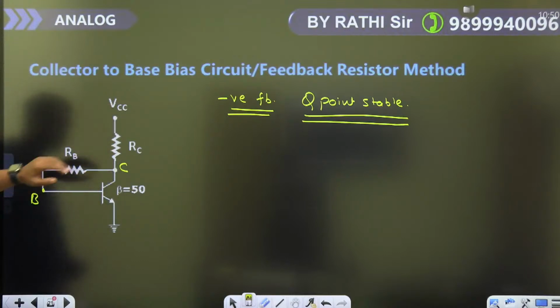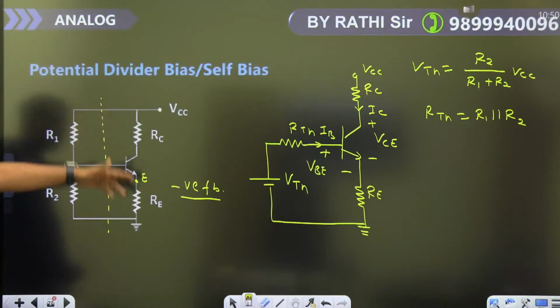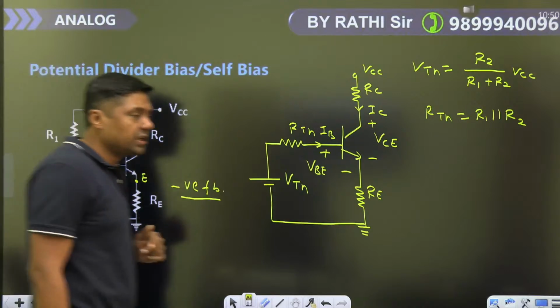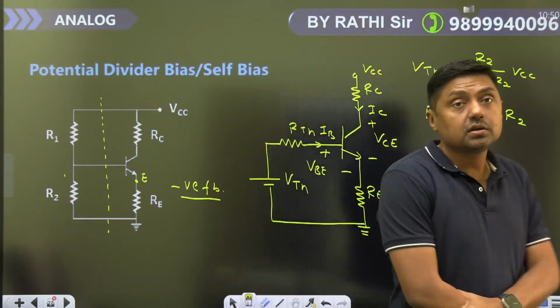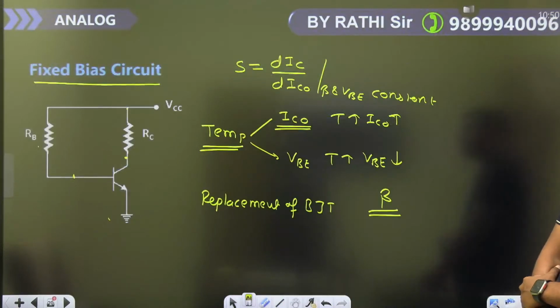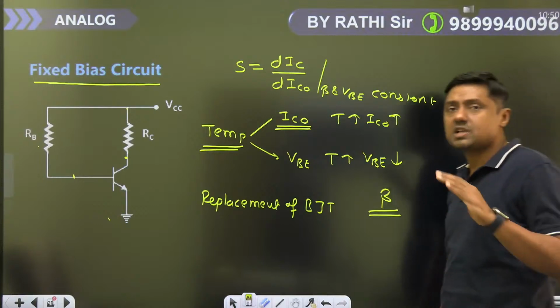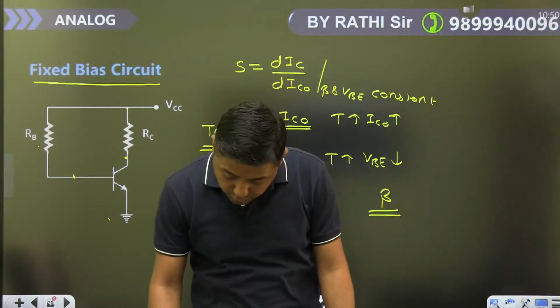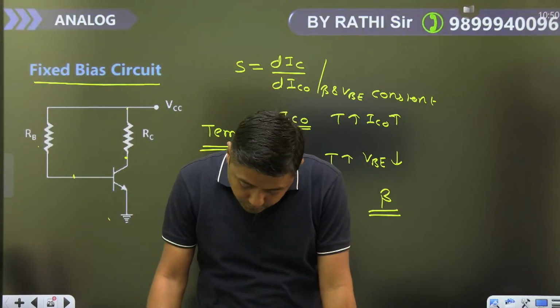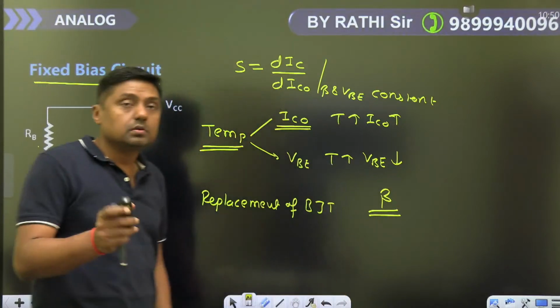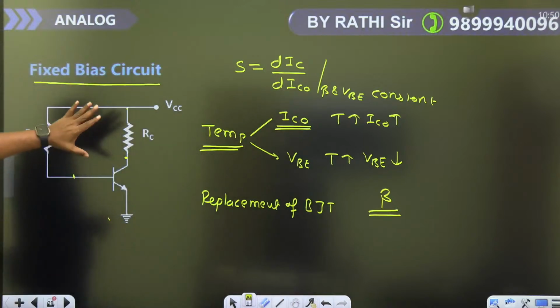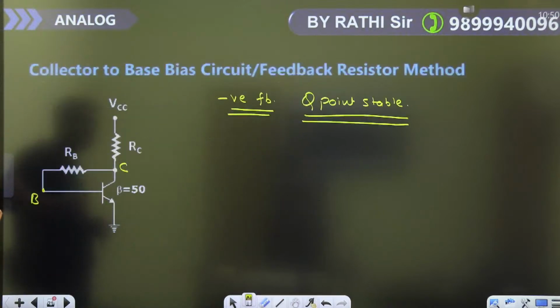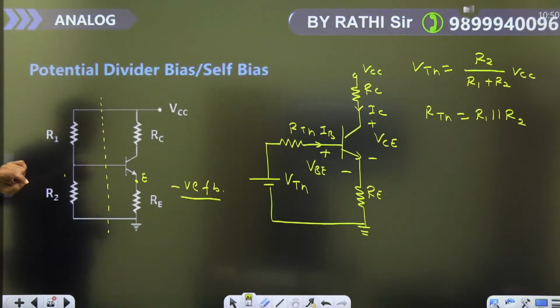यहाँ देखो जैसे ही आपने फीडबैक लगाया सप्लाई आपको बढ़ाना पड़ेगी क्योंकि एक्स्ट्रा आपका नेगेटिव फीडबैक के कारण सिस्टम का गेन क्या हो जाएगा, कम हो जाएगा। यहाँ देखो एक्स्ट्रा कंपोनेंट लगाना पड़ रहा है RE R1 R2, सप्लाई आपको इंक्रीज करनी पड़ेगी क्योंकि गेन आपको क्या हो जाएगा रिड्यूस हो जाएगा। तो जहां भी आपको लगता है फिक्स्ड बायस सर्किट जहां पर टेम्परेचर में वेरिएशन ज्यादा नहीं है वहां पर आपको सर्किट को क्या यूज करना चाहिए, राइट, you have to use what circuit in fixed bias mode, right? Now this is a collector based bias circuit and that is what potential divider bias circuit.